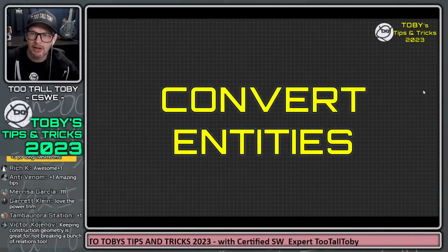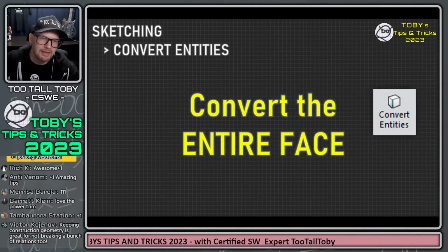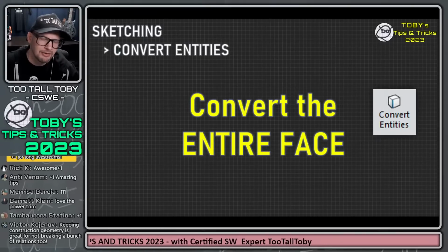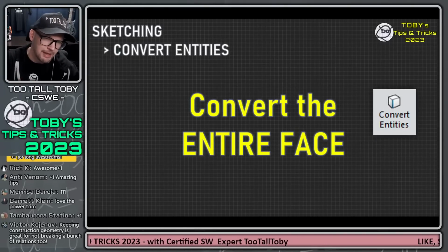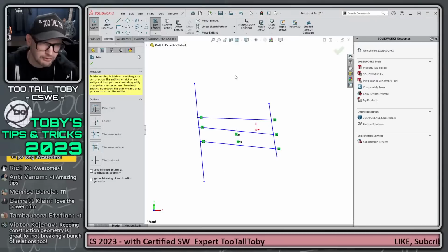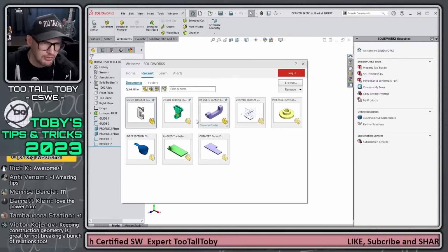All right, next let's talk about convert entities. One of the biggest things that I try to remind people about convert entities is that you want to convert the entire face when you're working with convert entities. And so what I mean by that is if I have a model like this,